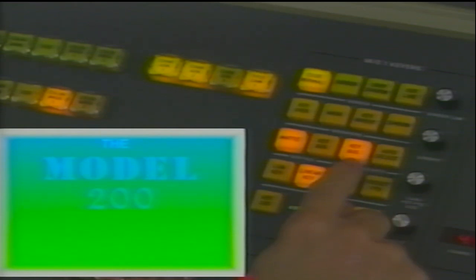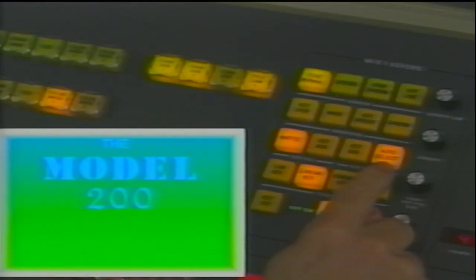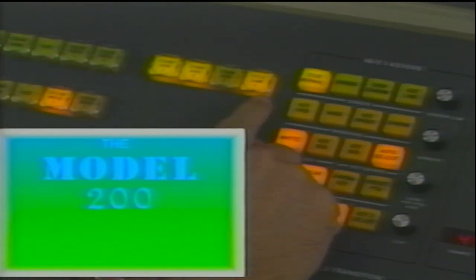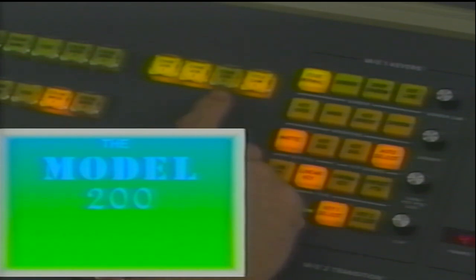Now the luminance, saturation, and the hue of the matte fill can be adjusted to the desired color. Notice at this time that we are keying from the video generated in the character generator rather than the key signal from that device. To utilize separate key signals, the Model 200 provides 6 inputs for each mix effects and 4 inputs for the downstream keyer. When Auto Select is enabled, the Model 200 derives its key source from a second bus in parallel with our key fill bus. In this case, we've chosen a key with a previously assigned personality.